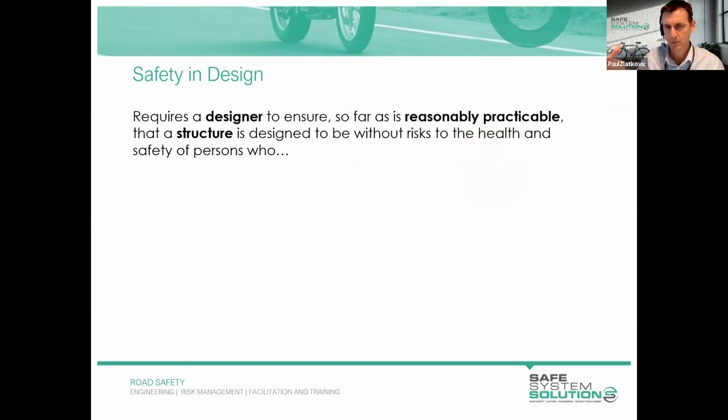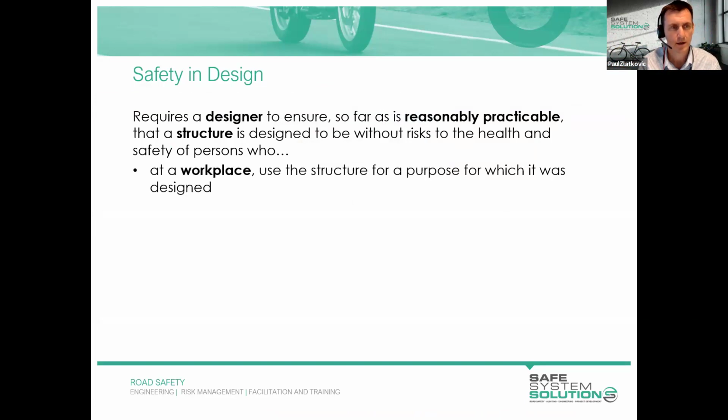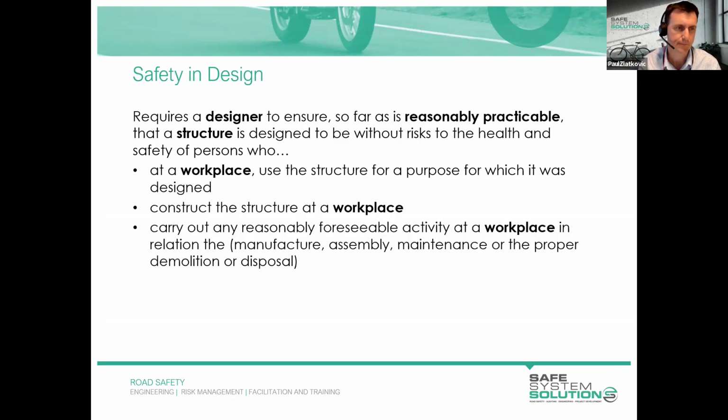I just want to go over quickly what we were doing yesterday, introducing those terms, introducing safety and design. What safety and design is, it requires that a designer ensure, as far as is reasonably practical, that a structure is designed to be without risks to the health and safety of persons who, at a workplace, use the structure, construct the structure, carry out any activity at the structure.